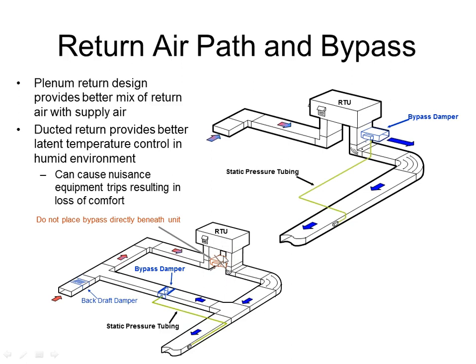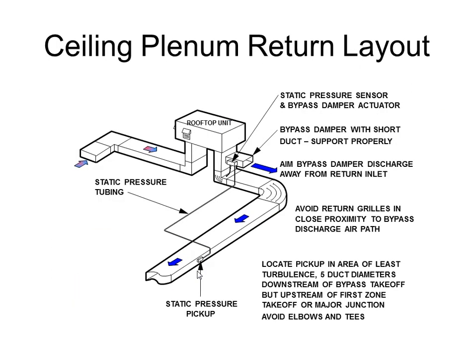And then you're discharging 140 or 150 degree air to the zones, and that's going to stratify and maybe trip your high limit supply air temperature, and nothing good is going to come when you put them in that location. So we're going to discuss little rules to give you a little bit of guideline here.